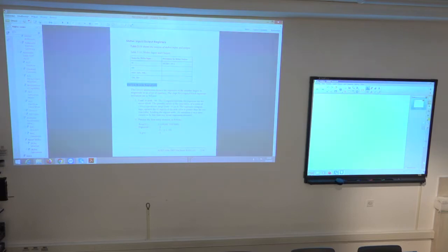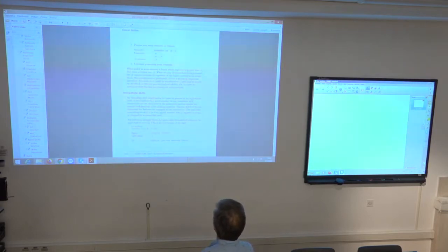And this particular operation is useful in the implementation of the fast Fourier transform. When you implement the fast Fourier transform, it is useful to always keep the data normalized, to have the data values at the leftmost position in the register. This way you avoid the round-off error of the computations. So that is the reason why this block exponent detection is a useful instruction.